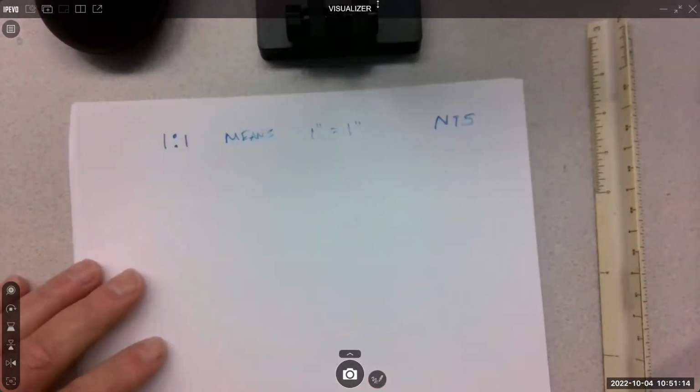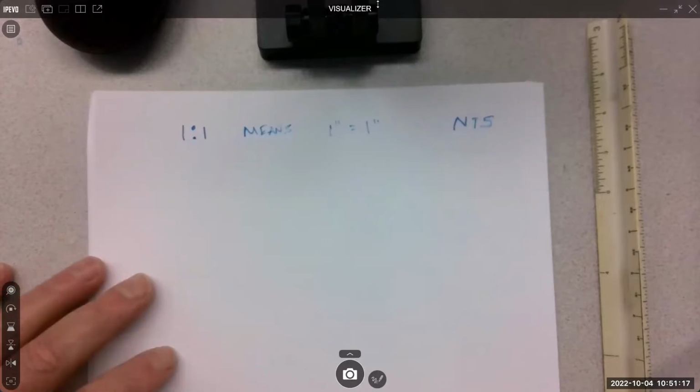You'll see that at times. That usually means they produced a drawing, but the drawing's super big, and then they just use the copier to reduce it down and get it on a normal piece of paper. Then somebody takes a red pen and writes NTS. Like, this is not to scale, but here you go. Good luck, right? So we really should not be scaling drawings anyway. We're just going to read the numbers on the drawing. You're not going to take a scale and flop it down and try to figure something out. If something's missing, you go to the source and say, you have a missing number, we need that number.